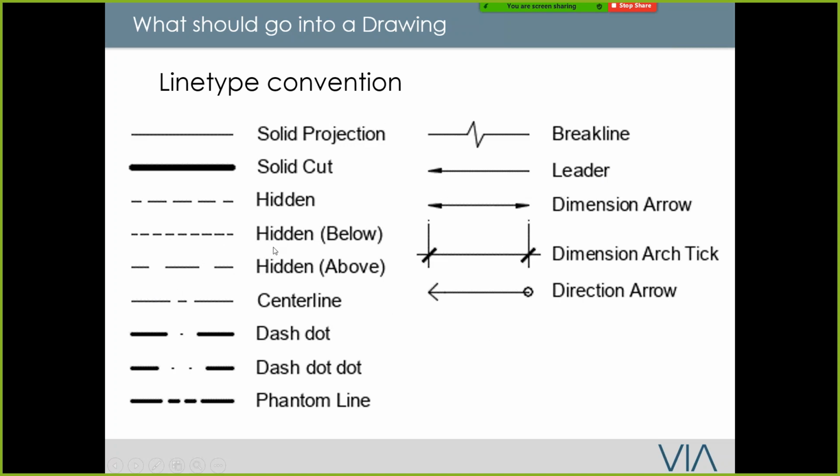Just note the differences, because sometimes people put in the hidden line below as really thick, like a whited-out separation. Convention says that below will always have a really squished hidden line, whereas above always has a wider hidden line.